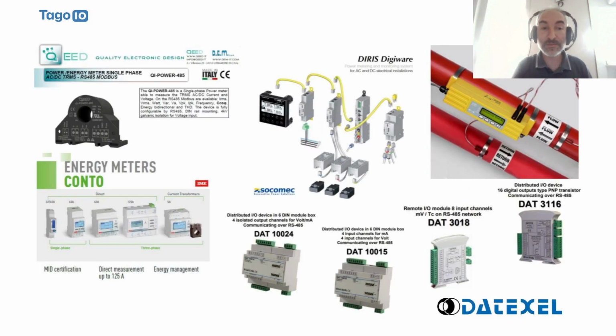As I told you before, with the Modbus, you can use any kind of Modbus RTU RS485 device on the market, and you can use it to measure energy consumption, from single-phase energy systems to big three-phase plants or transformers. You can drive analog output, you can drive digital output, or you can change parameters on inverters or other kinds of devices. You can read the heat using a heat meter, or you can also chain up to 31 different devices on the same line. So it's a very easy way to add LoRaWAN, wireless connectivity, to the devices.